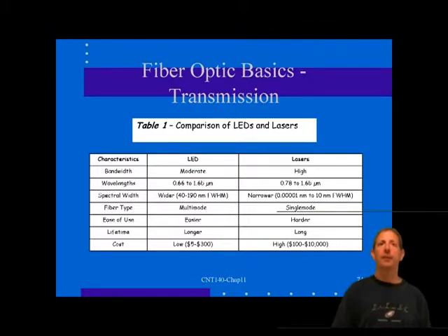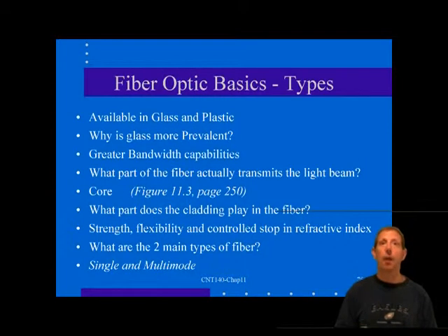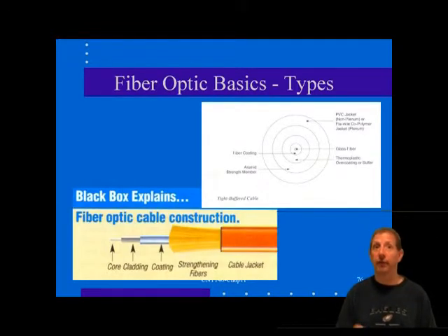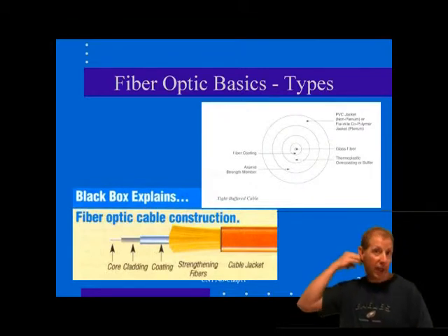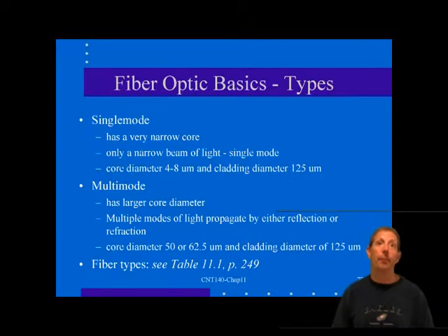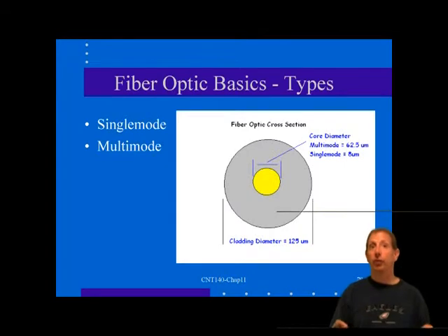The loose buffer fiber optic cables are most often used in multiple fiber runs between distribution points, such as telecommunications rooms. This type of cable is appropriate for structured cabling, backbone cables for campus backbone runs, and for runs to the multi-user telecommunications outlet assembly in our open office environments. Centralized cabling systems may use this type of cable effectively to run to a point of interconnection, such as a telecommunications room on a building floor. Individual cables may then be run to each user outlet.